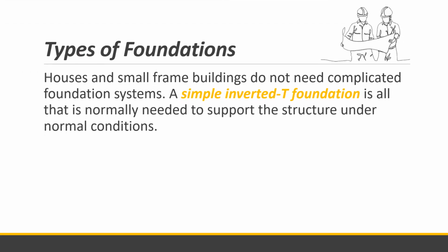So there are different types of foundations. Houses and small frame buildings do not need complicated foundation systems kasi usually 2-story lang or 1-story lang yung mga houses natin. So a simple inverted T foundation or spread footing, as we call it, is all that is normally needed to support the structure under normal conditions. So inverted T is yung ganito.